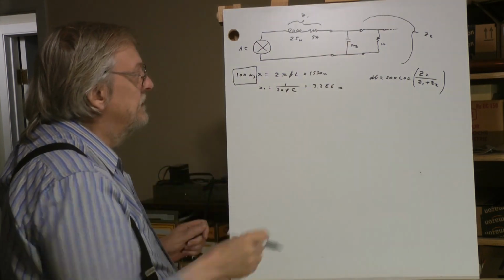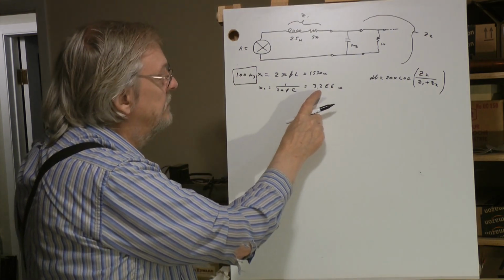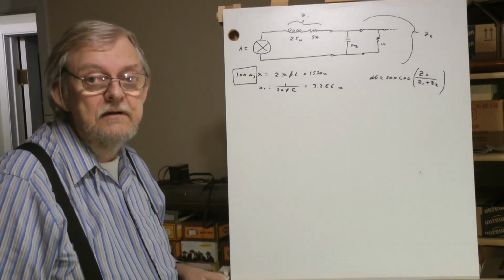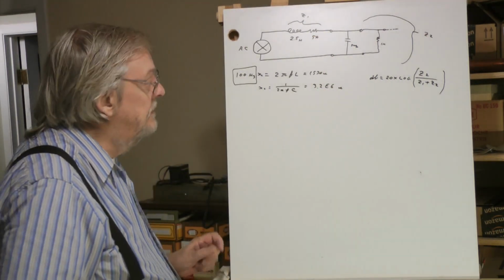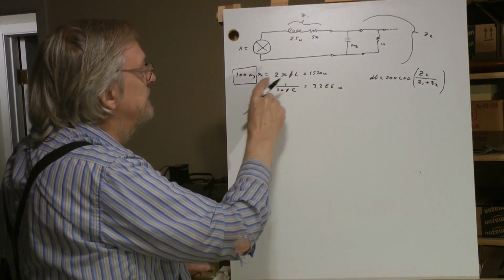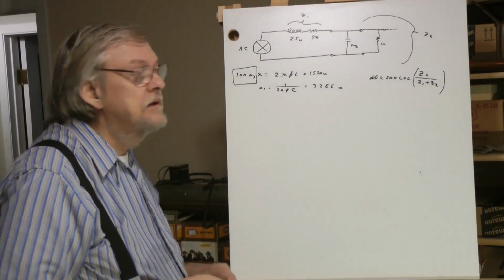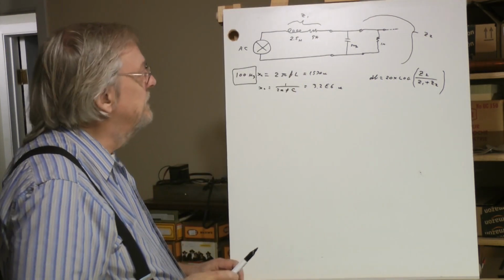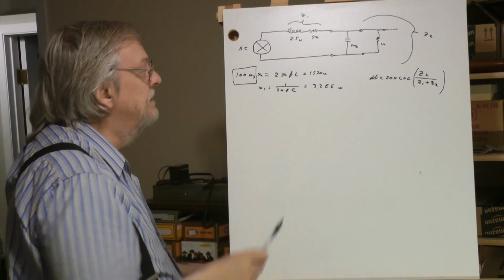Now you might think, well, is that going to affect the tone? Well, yeah, when you get up to a couple of thousand Hertz, that goes below 1 million, right? So we no longer have a 1,000,000 ohm load. We might have 500K, 100K, stuff like that. So the high harmonics are going to be shorted out by that capacitor. Now the coil, as the frequency goes up, this number is going to go up, so it's directly related. So when we get up to a few thousand Hertz, or up into the harmonics, this guy's going to kill the treble. Your pickup automatically kills treble because of its inductance. Your cable kills treble because of its capacitance.